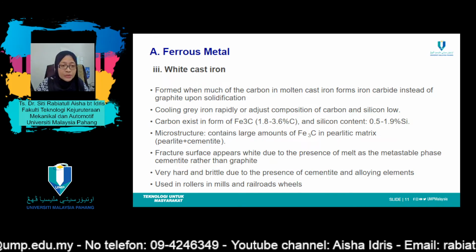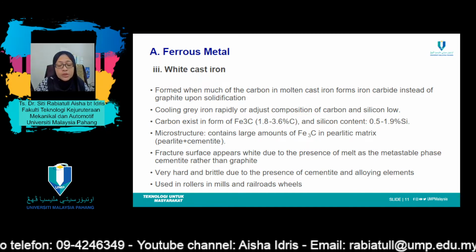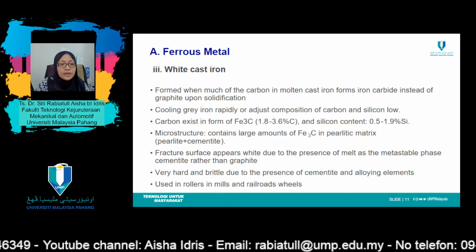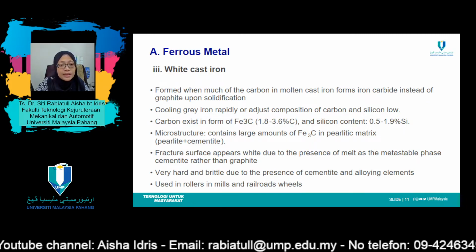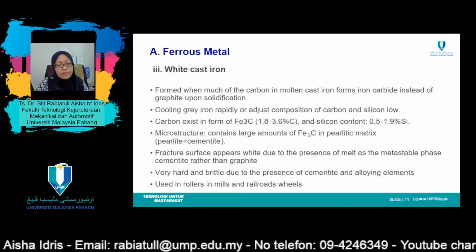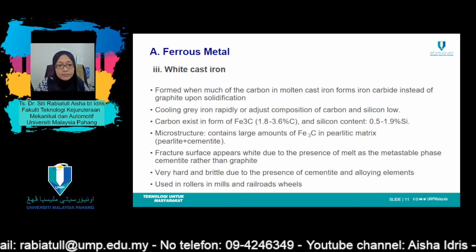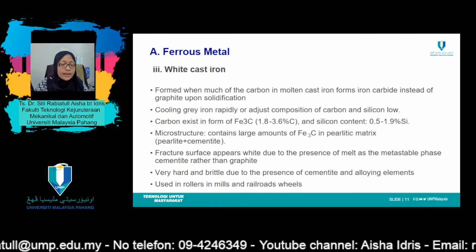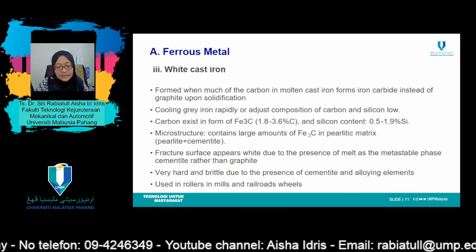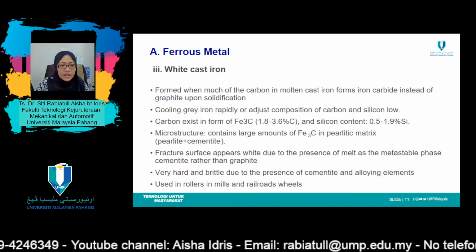White iron is extremely hard but also very brittle, to the point of being virtually unmachinable. Its use is limited to applications that necessitate a very hard and wear-resistant surface without a high degree of ductility, for example, a roller in rolling mills. Generally, white cast iron is used as an intermediary in the production of yet another cast iron, malleable cast iron, or malleable iron.